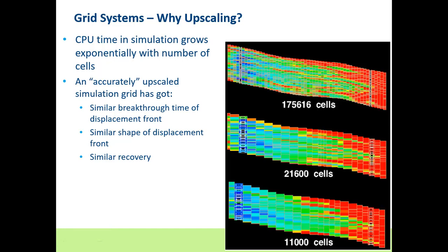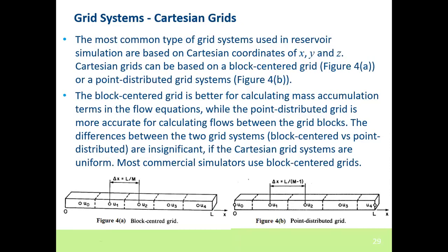So in upscaling, what you're basically doing is reducing the number of simulation grid blocks in such a way that the general geological framework is still honored, but it will require less CPU time for you to run your models.